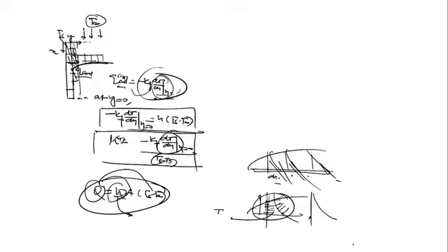Same thing, if you recall, I told you that you can calculate the friction coefficient as tau w upon half rho u infinity square, that is mu into du upon dy at y equal to 0 upon half rho u infinity square. But this requires the information about the velocity gradient at each and every point on the wall.